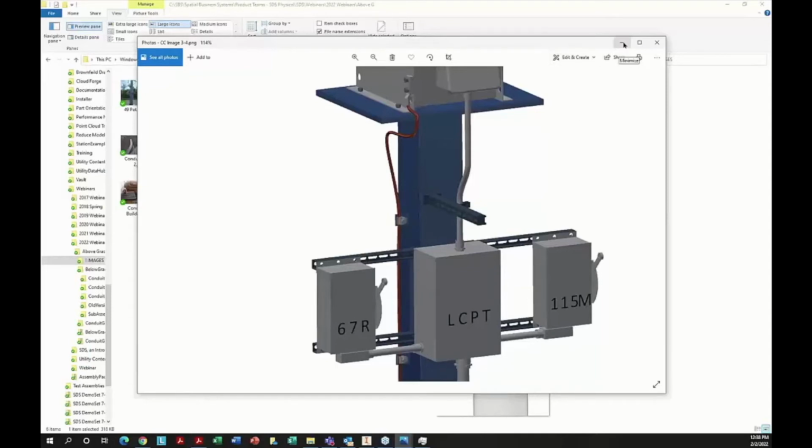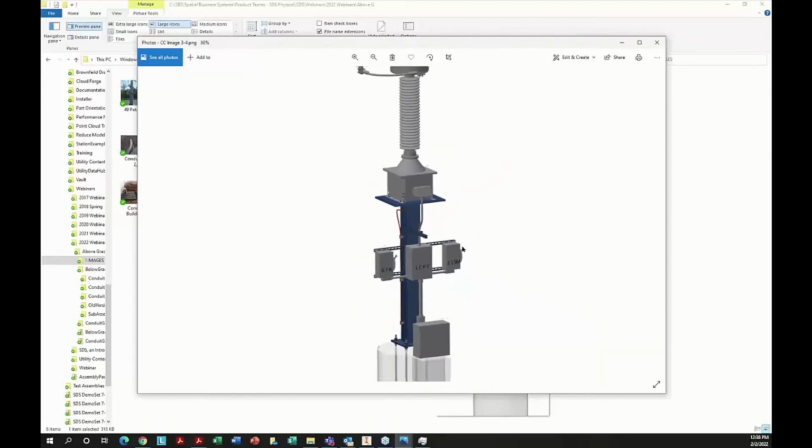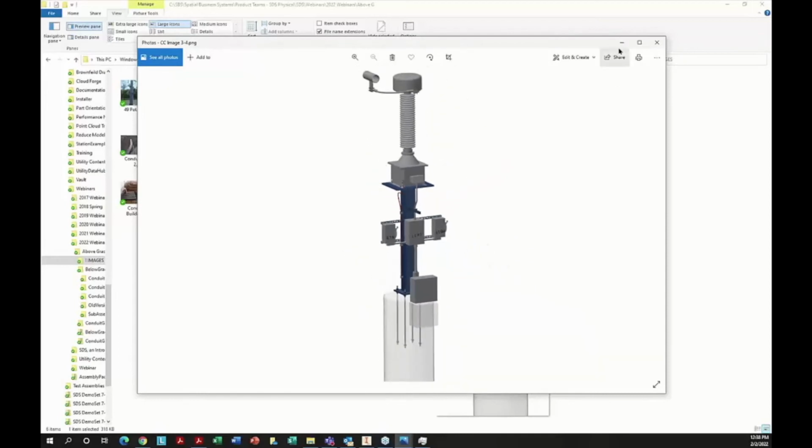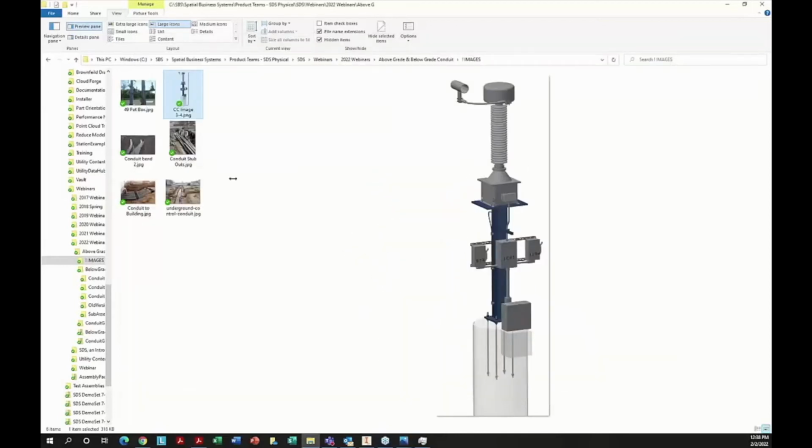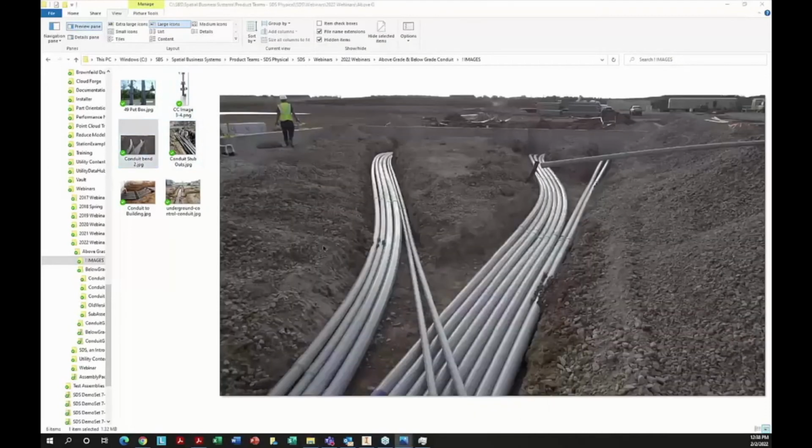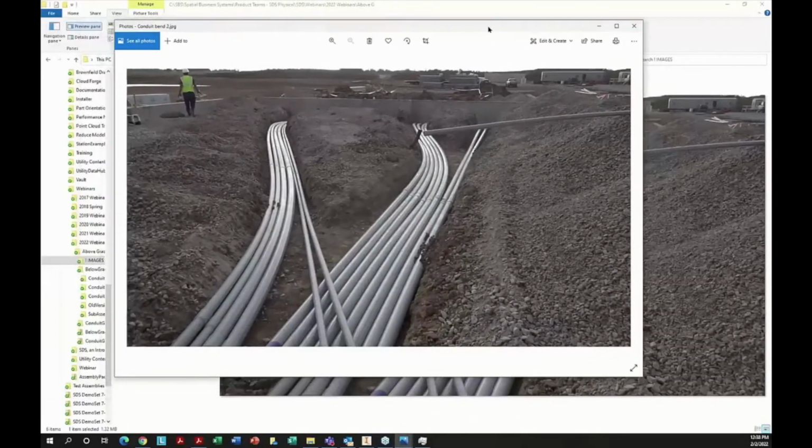So I just wanted to point that out here because I really like this little island subassembly. I think it's a real nice one. Shows a lot of things in here. But when we're looking at conduit, what actually happens is they'll dig a shallower trench. They don't dig a really deep trench or lay it all in. This could be 3 inches or 4 inches round. It's about that size, it looks like to me. And they're bending it. Either they heat it to bend or just the PVC is allowed to bend this way.